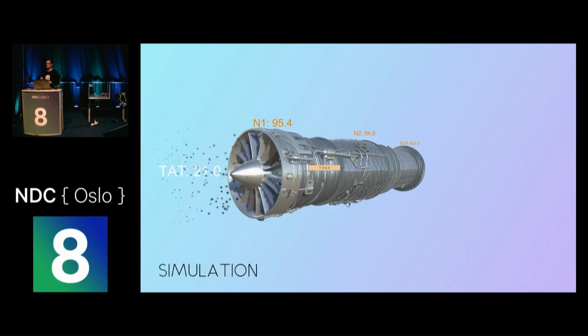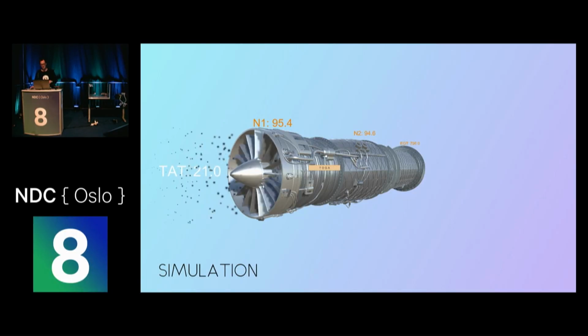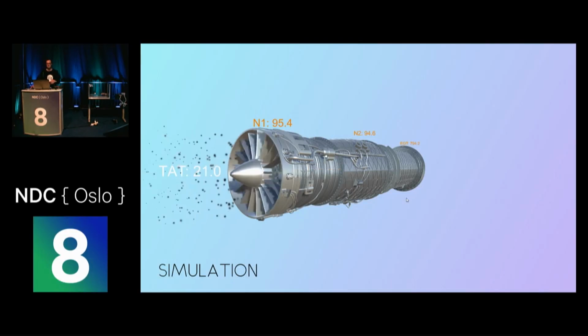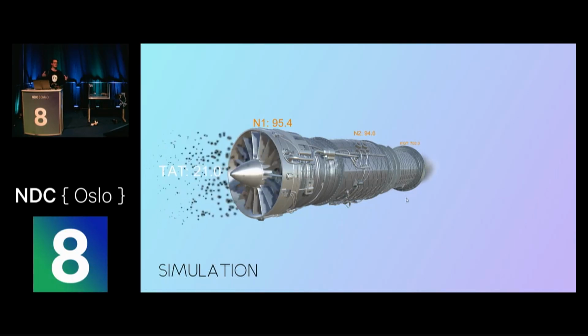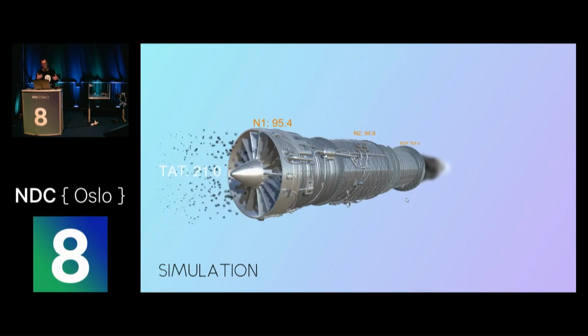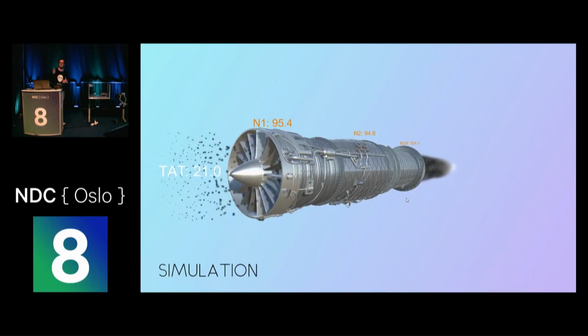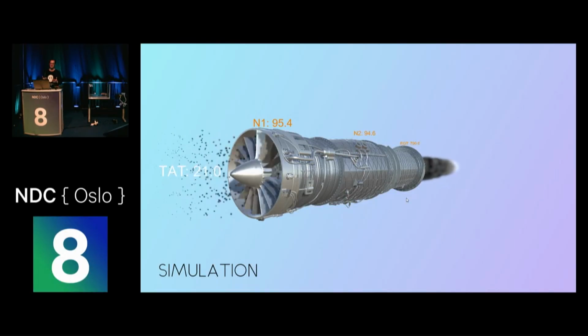So what they do next is to add a little bit of thrust. They go to the runway, and when they're on the runway, they hit something called TOGA, which is take off and go around. Once they do this, this will then spool up and start applying thrust to the airplane. And once the pilot releases the brakes, it's going to start rolling and eventually take off at the correct speed.